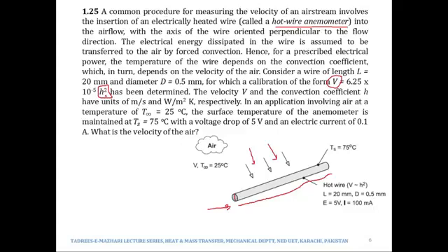So it would be somehow measuring q, and A would be the area of this wire, and ΔT, and with the help of q = hAΔT, the instrument will first calculate the value of the convection coefficient h, and then this equation would be programmed into it already, and with the help of this equation the instrument will calculate the value of the velocity of air, and it will show us the value of the velocity of air.